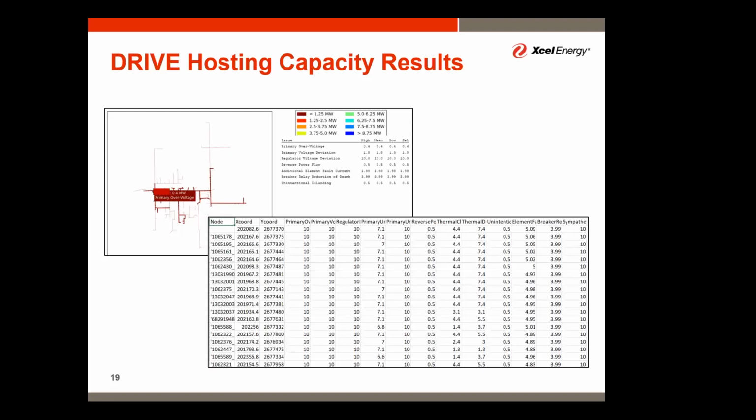If you could know the actual values, you could see, okay, if I want a project that's going to be larger than the minimum because it's just the voltage, but I want to stay under the thermal violation number, I could size my project to meet that if you had all the data that's in this table. But what's provided in the map now, where you only have the name of the most limiting criteria and not the values that go along with each, doesn't give you that increased information. Understood.